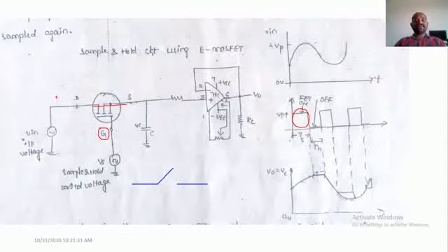Okay, so whatever information is there at the drain will be seen at the source point, and whatever information we are having will be stored in the form of charge across the capacitor. It will get stored inside the capacitor. After some period of time, since these are continuous pulses, we are applying 0 volts now. Because of that, this particular gate will get open. Means this particular switch is open. Previously it was a short, now it is open.